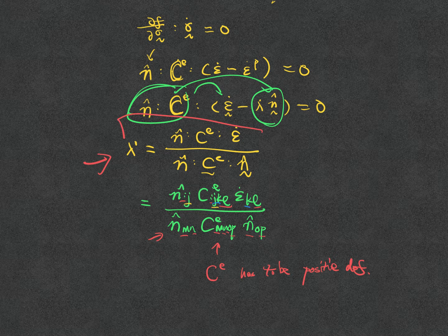I have an analytical form of how much plastic flow I generate, the strain rate I generate, and I already know the plastic direction, which on any part of the yield surface would just be the normal. So I have an easy time. I know the magnitude, I know everything. I just need to introduce something called a return mapping algorithm or radial return algorithm, and what I want to talk about is this algorithm.